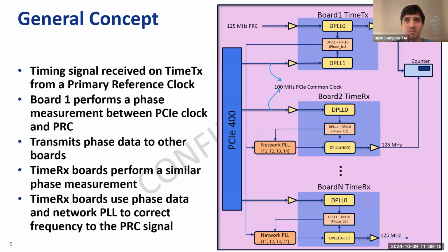Spread spectrum is a must for us, especially when we have higher lines, like our PCI here and other things. Again, it's to reduce EMI, otherwise the implementations were not working. Then spread spectrum was introduced and, okay, we stretched a little bit more and things worked. So, Greg, what do you think?